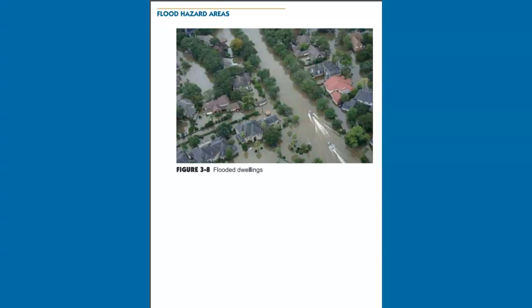hazard areas. Site development in designated flood hazard areas must meet special requirements for flood-resistant construction to minimize damage during a flood event. State or local floodplain management ordinances often supersede the IRC provisions for flood-resistant construction. Requirements are similar, however, and are designed to satisfy the minimum standards set forth in the National Flood Insurance Program (NFIP), managed by the Federal Emergency Management Agency (FEMA). Figure 3-8. Ref. R 322.